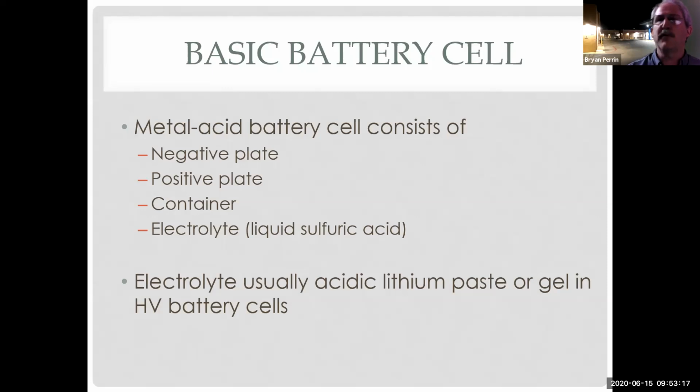If I'm doing golf carts or forklifts where they run 36 volt battery setups, I may be rebalancing them. Or if I'm running off-grid solar, where I'm running multiple batteries, I need to balance the battery array. So I will be manually going through and using a tool called a hydrometer and adding acid and adjusting that. But for cars, we just don't do that anymore.